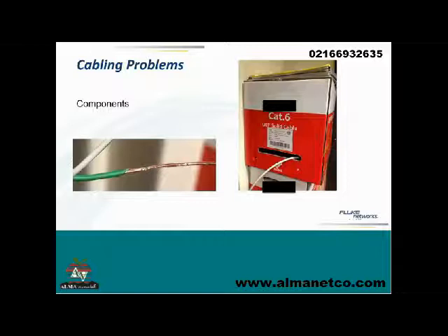But one of the ways to notice the difference is the fact that aluminum's a lot lighter than copper. So literally, we have had customers send us boxes where there are metal weights in the bottom of the box to make it as heavy as a copper box. So if you pick it up, you think you've got a box of copper cabling, but you don't. And you remember I mentioned some of those other strange measurements like transverse conversion loss. Those can find things like copper-clad aluminum cable.